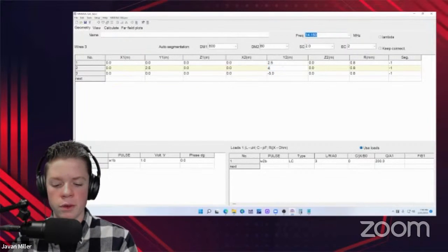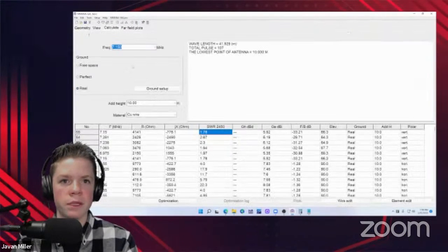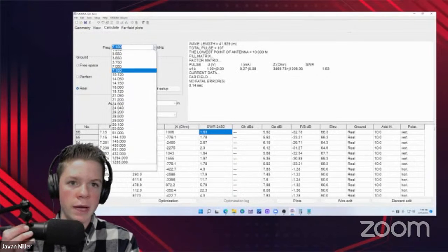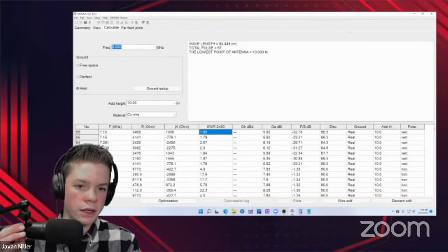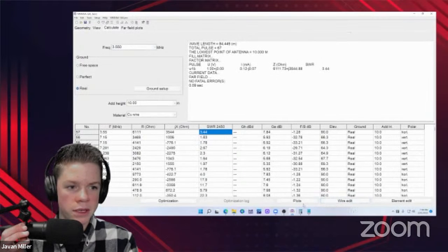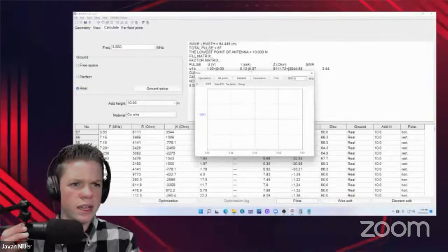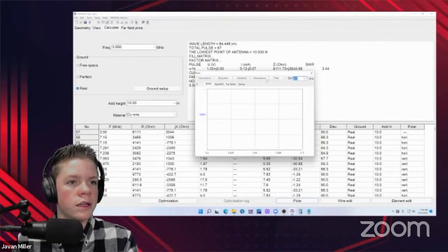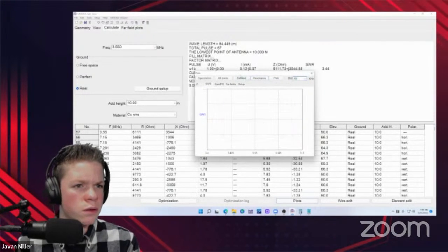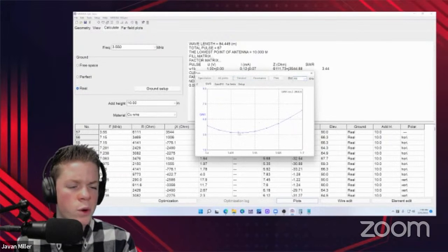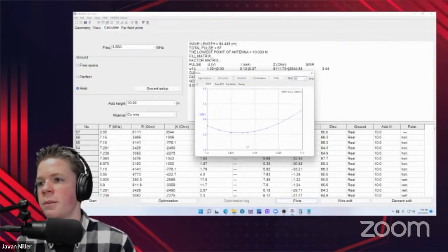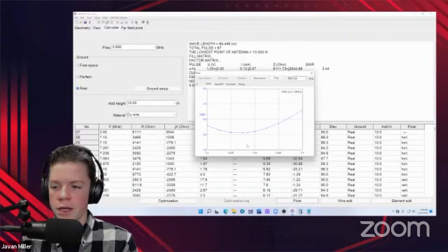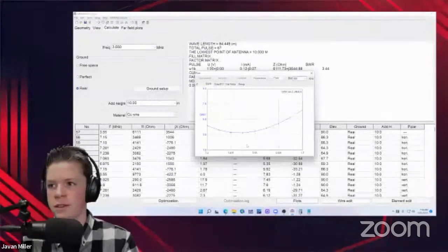So let me shorten the antenna even further to 40 meters long, and let me go back to 80 meters to see where the dip is. I have to bring it a little bit wider here. So yeah, this is still set. The lowest SWR is at the bottom of the band. So we could improve this a little bit if we would increase the inductance.